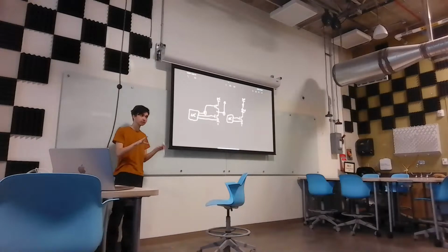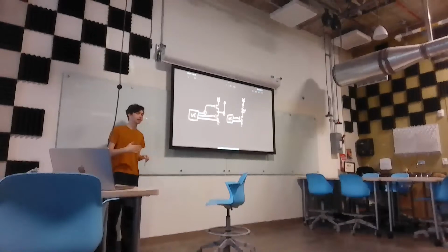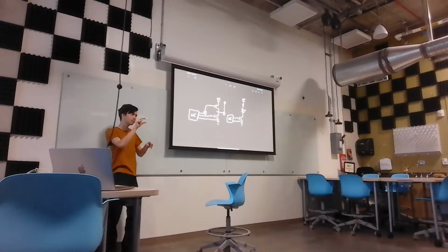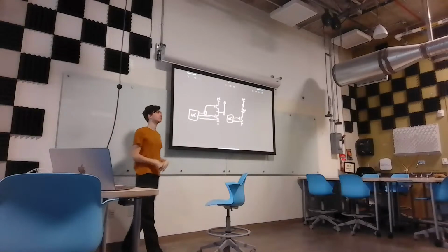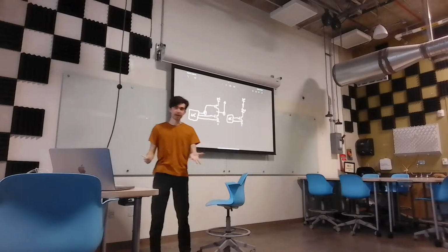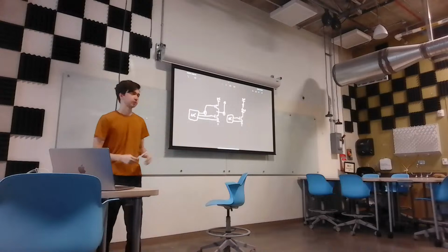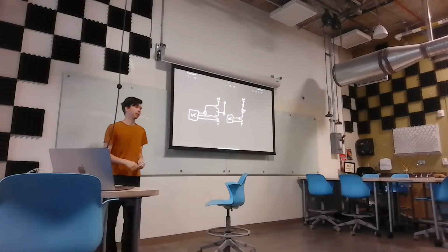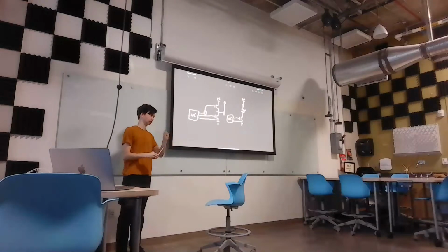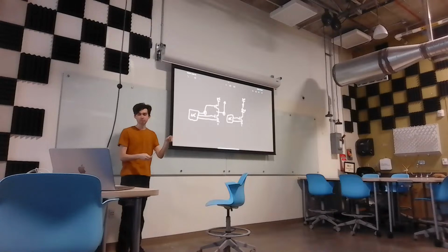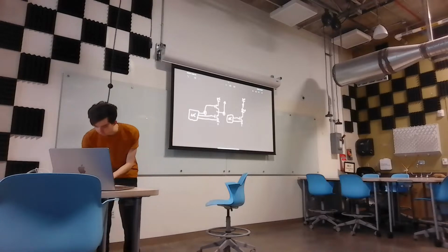What we're doing is it's still an N-channel MOSFET, but when we turn it on, we need to somehow keep a voltage on its gate that lifts up with it. The method to do that is called bootstrapping. It means you have a little capacitor that you charge up right here.